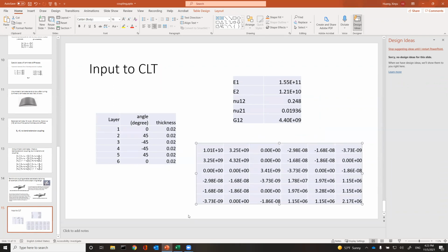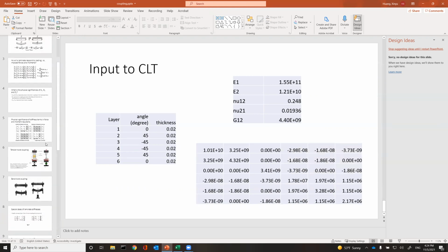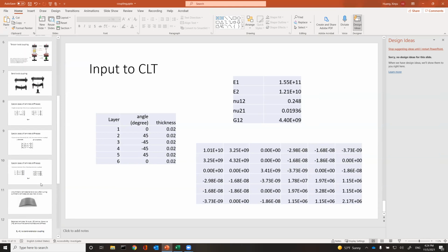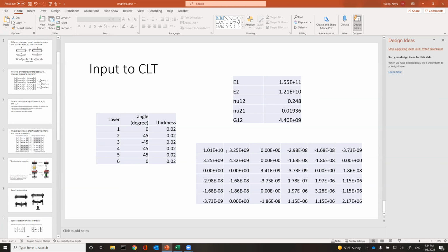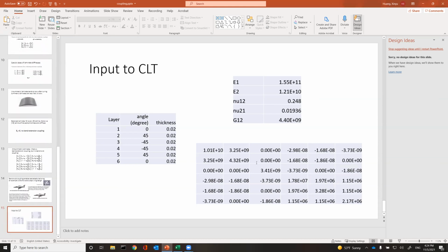All right, the dominant feature of symmetric laminate is the B matrix is essentially 0. So this matrix is all very small numbers, either pure 0 or almost 0 compared to other terms. This term, the same here. Symmetric laminate B matrix is 0. And your calculation should show the same thing. Okay. So we're talking about the symmetric. All right, so what I want to do now, is everyone done with this? Everyone done with this? All right, Thomas is done.